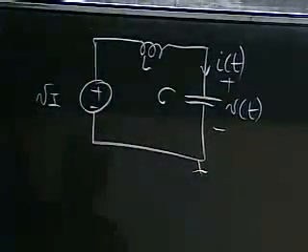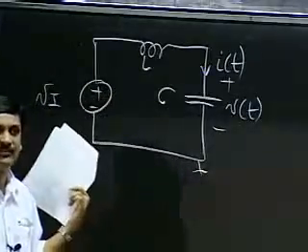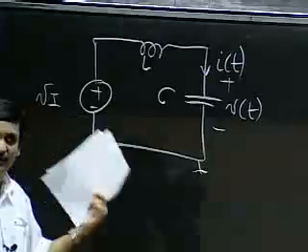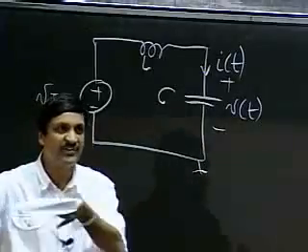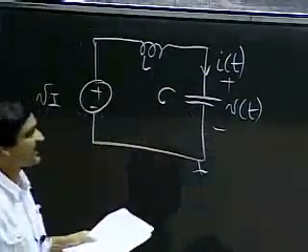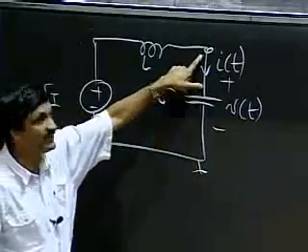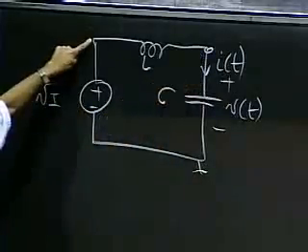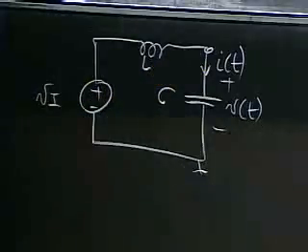We're going to proceed in exactly the same manner as we did for first order differential equations. Write the equations down and just go down the same set of steps, but get to someplace different. So we're going to start by writing a node equation for this node here. That's the only node for which I have an unknown voltage. The node here is VI, so I need to find this. There's just one unknown node voltage. And I'm going to need some element laws.